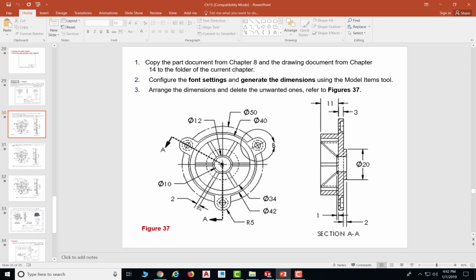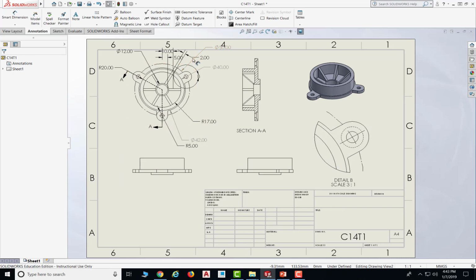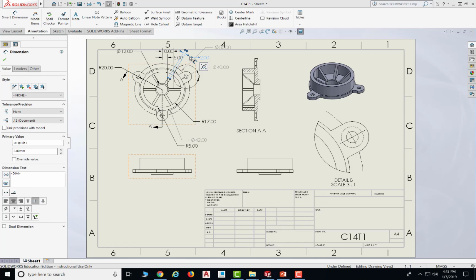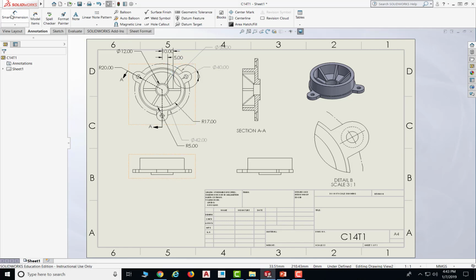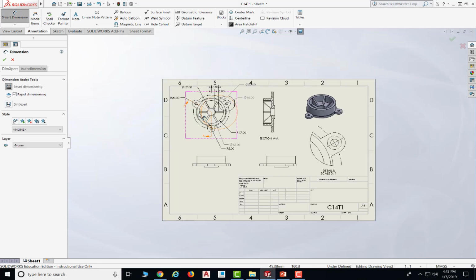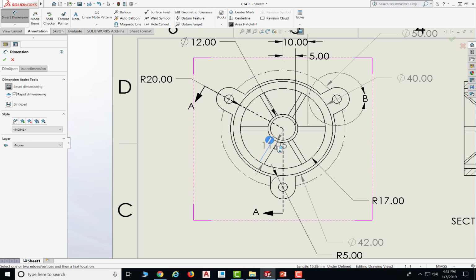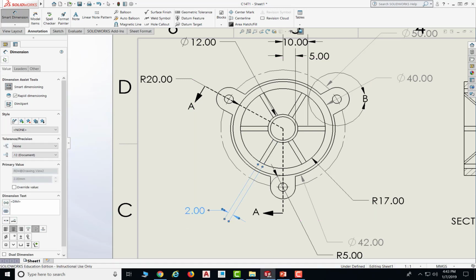And the distance is 2, and I had a 2 above instead of below, so I would have to delete this because it's pointing out. But we want to dimension this too, though they're the same. We're just doing the same thing that the drawing says. So you could zoom in and select these 2 edges, make it 2 and say OK for that.